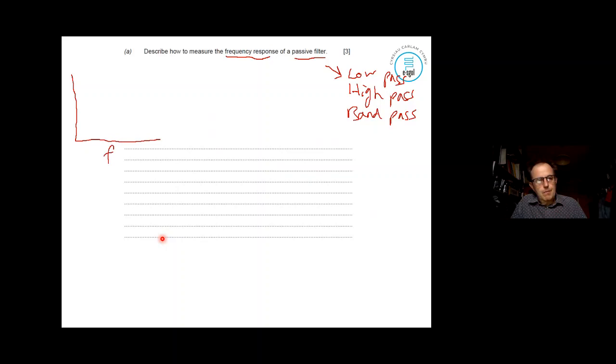So just remember, frequency will change. What happens, you basically get a different output voltage on each one. Okay, so that would be a diagram which shows basically a low pass filter. What we've got on these filters is a bandwidth. And that bandwidth is the range of frequencies over which you can get a decent output. Right, the point there we've got is the 70%, 0.7.